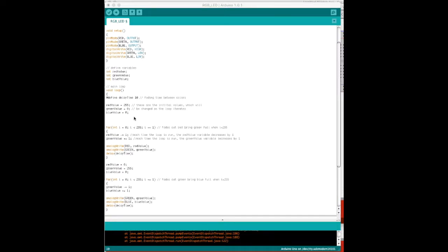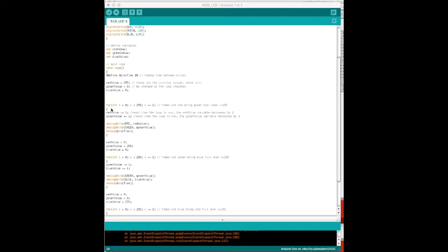So to start off, we're going to have a max on the red value and then zeros on the others. So you should see in the very beginning at least an all red LED. For loops. So this is the for loop standard format for C or C++. It starts off by creating a counter. So we're creating an integer named i, and its starting value will be 0. You could start this really at anything, but usually you would start at 0. No reason not to here. And then you're going to count your way up.